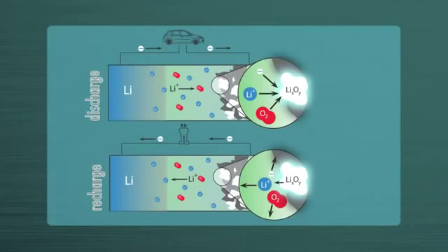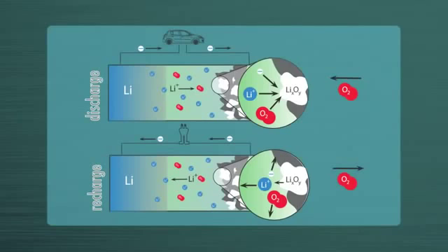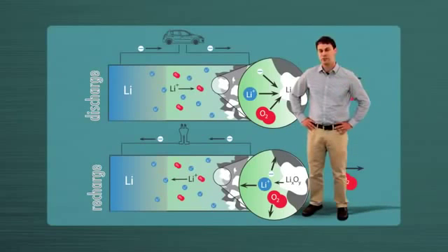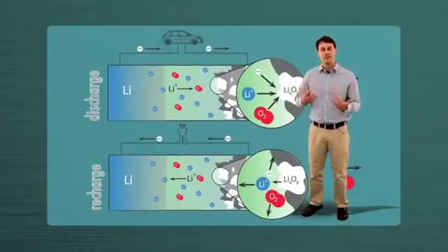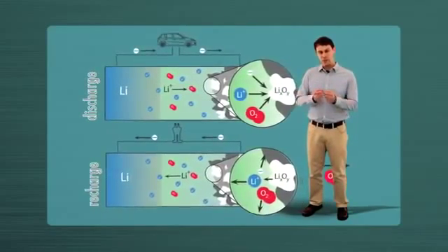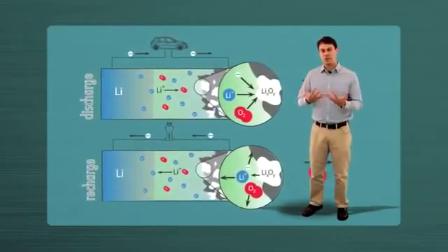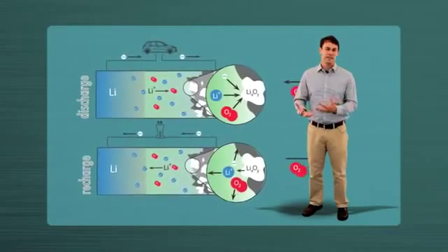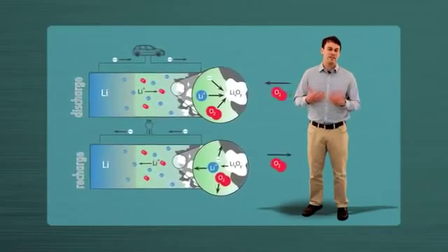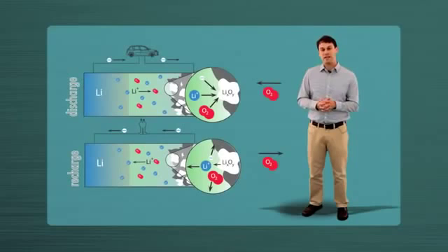the cathode. So the mass advantage of this system, as you can see, is based on the fact that one of the reactants, oxygen, does not have to be stored on board. We can flow it in as we need it, and that's represented by the oxygen molecule on the far right edge of the slide. So we call this type of battery a precipitation dissolution system, because in the course of operating the battery, we nucleate and grow one of these peroxide or oxide phases. And then when we recharge the battery, this phase has to decompose or dissolve back into the electrolyte.